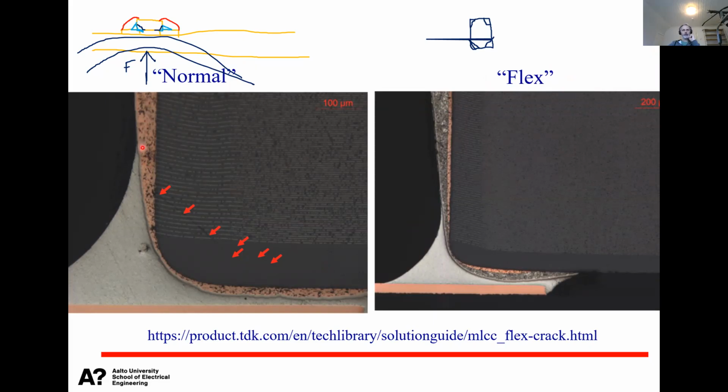So here, this contact metallization is rigid. It's copper and glass, so it's basically a thick film, rigid contact metallization. But this contact metallization here has only a very thin copper layer, and on top of that there is a silver layer, which is not made with thick film, it is organic. So it's basically a conductive silver glue. It's silver flakes in an epoxy matrix.